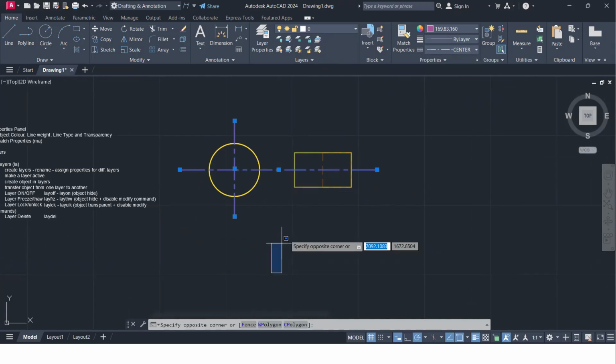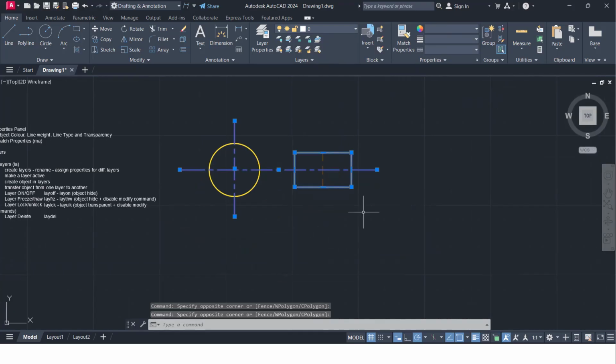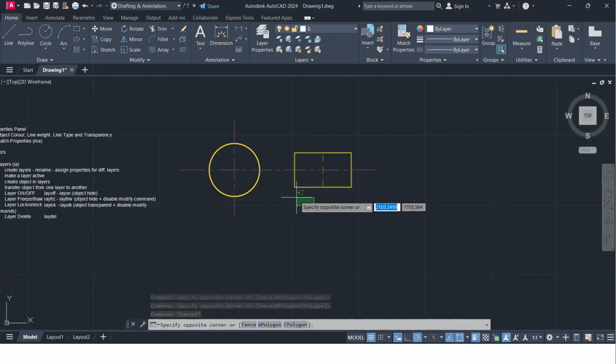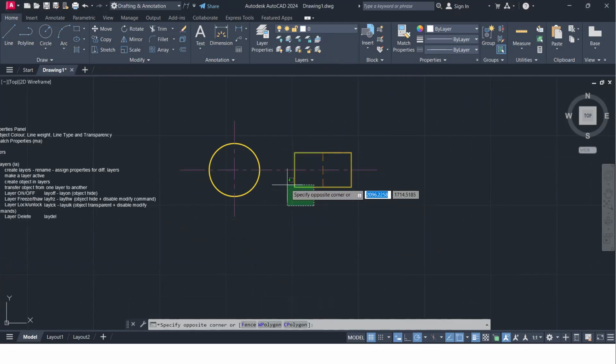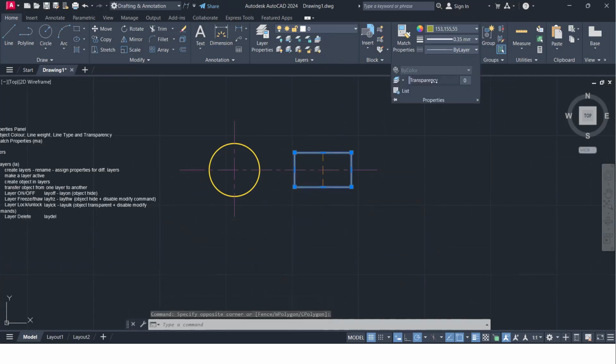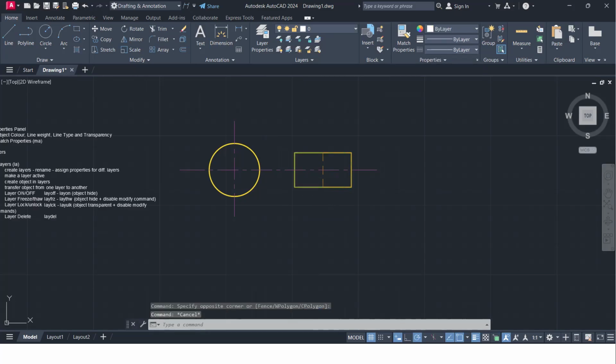And the transparency option is mostly used when, suppose I want to select this line and apply it here. I select this line, and then this is my line. Okay. I select this line and then I want to apply transparency here. Then what you do is just click on the transparency and increase the transparency value. Okay. 0 to 90 is the transparency value.